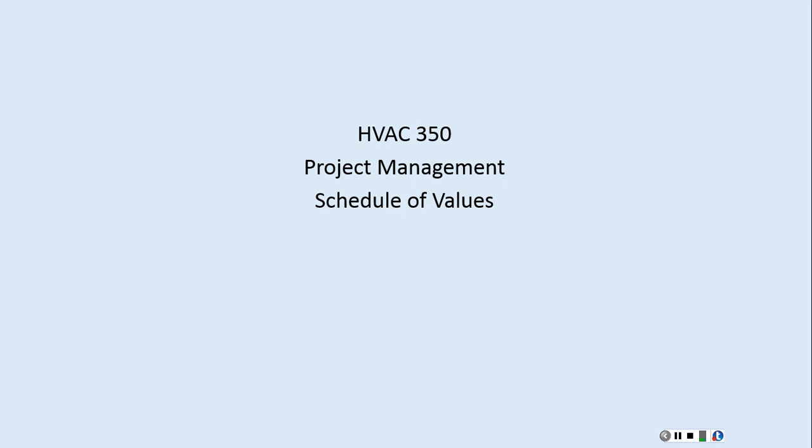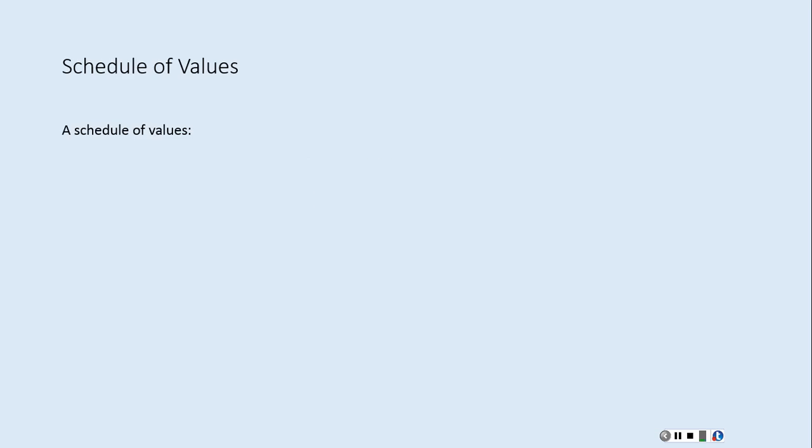What this Schedule of Values does is break the entire project down by individual categories so that the superintendent, general contractor, or construction manager on the project can validate that we have a certain amount of work done that we say we have done, to protect the owner's interests so they don't overpay for items that aren't completed on a project. A lot of words just said there, but it's really a straightforward document.